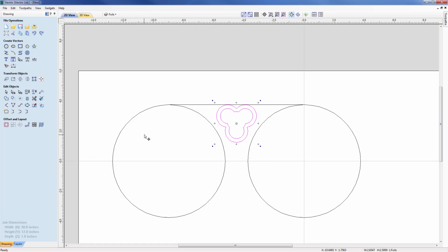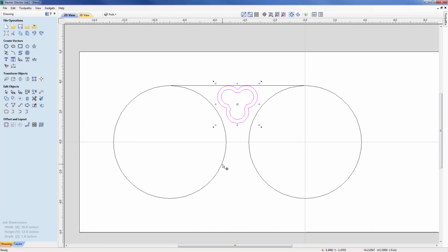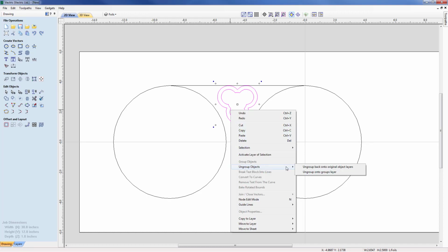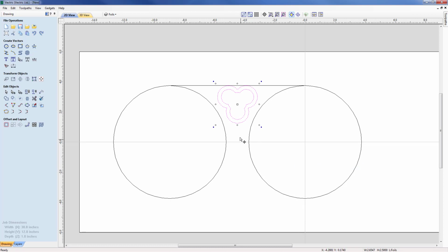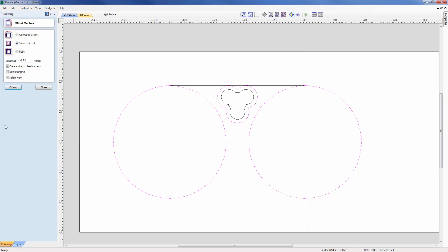So the next stage is to start making some modifications to our circles to fill in basically the pieces at the edge of our sort of central trifoil here. So with that now, I'm actually going to group these back down onto their original layers. So now they are simply two separate entities, and we're going to look to offset these three circles. So we're going to take this item, and this item, and now offset those together. They're going to go all outwards by 0.375 and offset those.